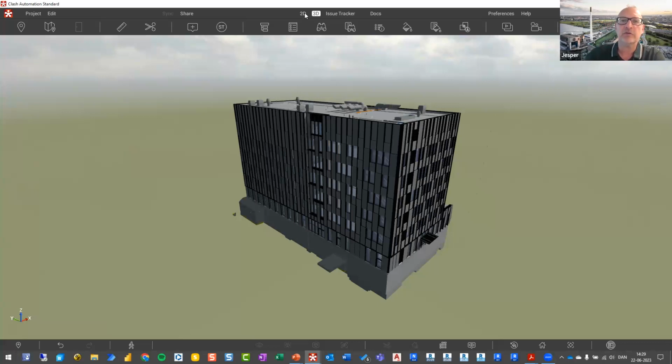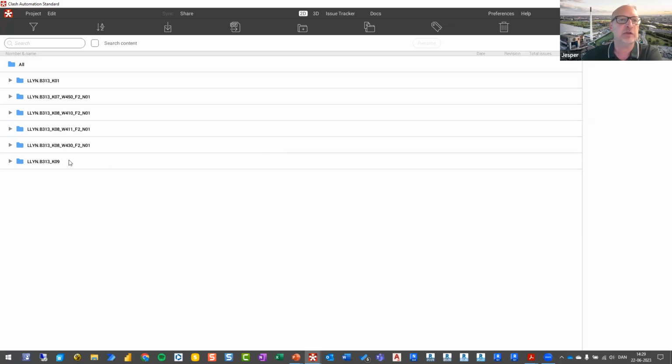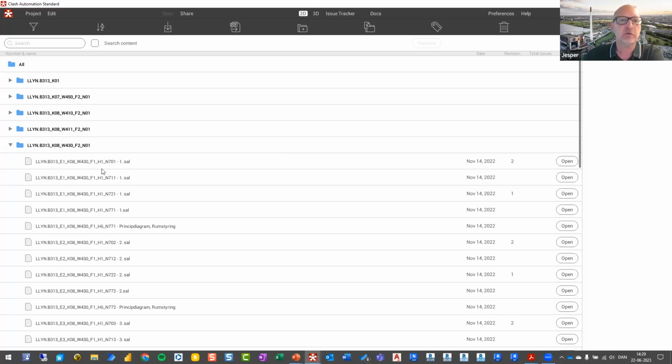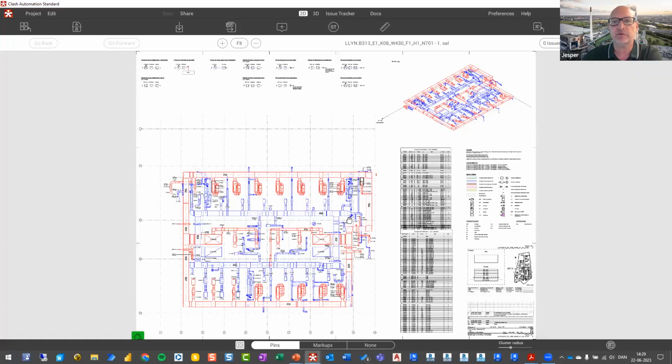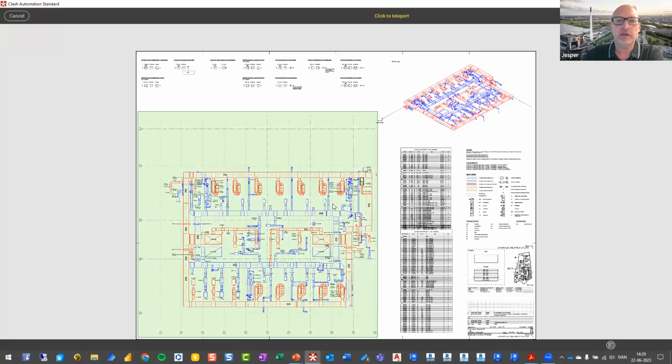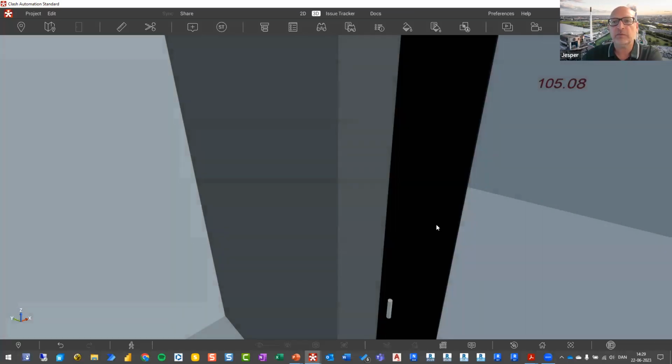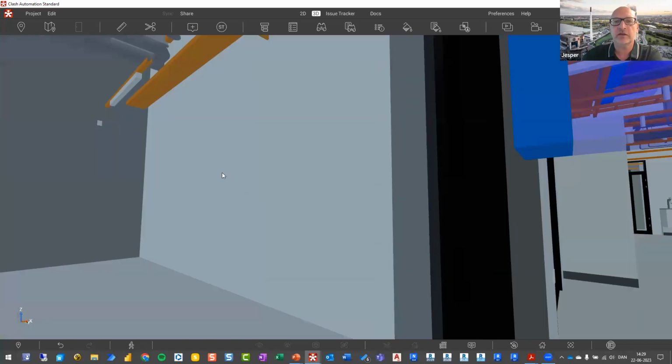But when we started out, you could also export 2D drawings to Revizto, so they could go in and see their 2D drawings in Revizto. As soon as we showed them how to jump from the drawing using the jump to 3D button, you get this square and it asks where do you want to go? I can just click somewhere within the green square, and it will take me to that place inside the model very quickly.